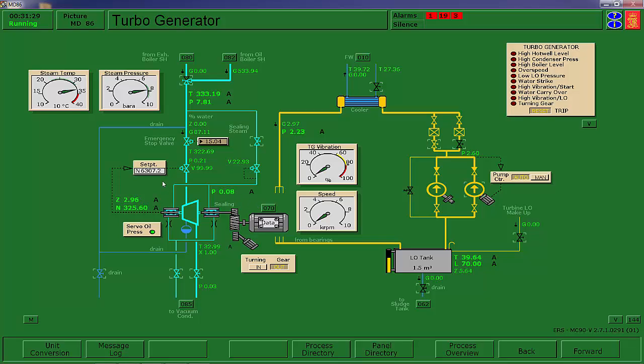So the one thing that I'm a little unhappy with in the simulator in this instance is that you're going to have to slowly open up the steam to it. This acts like a pump, not a generator. But realizing that, what you can do is crack it like this, get it turning over, and then go do other things and come back after 3 or 4 minutes and then go ahead and bring it up. If you try to bring it up too fast without warming up, you'll get excessive vibration. But again, this should start here, and what happens in real life, it will keep increasing slowly in speed until it gets up to 6,300 RPM.